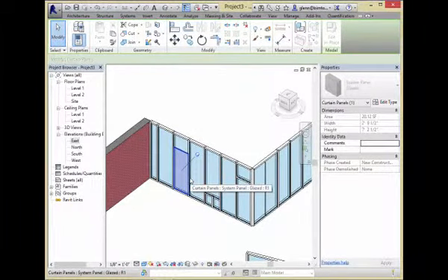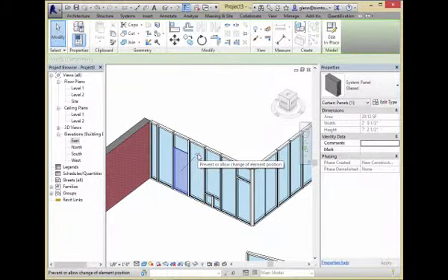Notice it's pinned right now because it came out of that pattern. So I'm going to unpin it so I can change it. In fact, since it's pinned, you'll see that I can't change it over here in the type selector. It's grayed out right now, so I can look, but I can't actually touch it. So I'm going to unpin it. That gives me the flexibility to make some changes. Okay, now we can start playing.